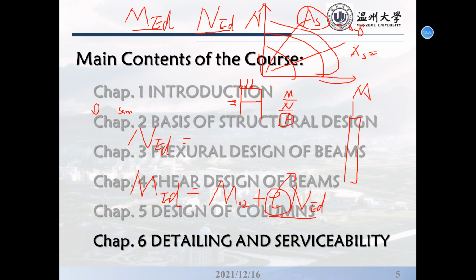And how to calculate this is essentially an empirical formula for us. It's L0, that's the effective height, right? Effective height I illustrated before. L0 divided by 400. If students forget, please go back to review the PPT. This is for the short columns, right?